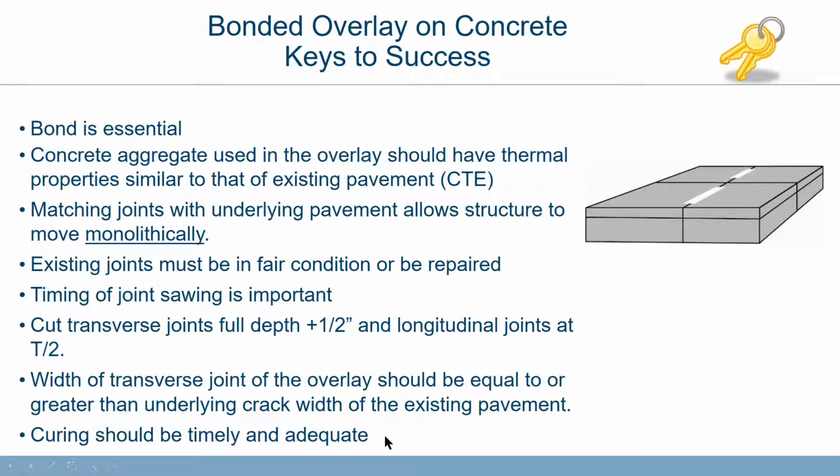Curing, again, should be timely and adequate, primarily in these bonded overlays, whether it's the thin bonded on asphalt or on concrete. The reason that the curing is so important is because you're dealing with usually a relatively thin pavement. And the hydration process needs to be assured in those pavements so that we can be sure that we get the proper strength and even the proper bonding in those types of installations.